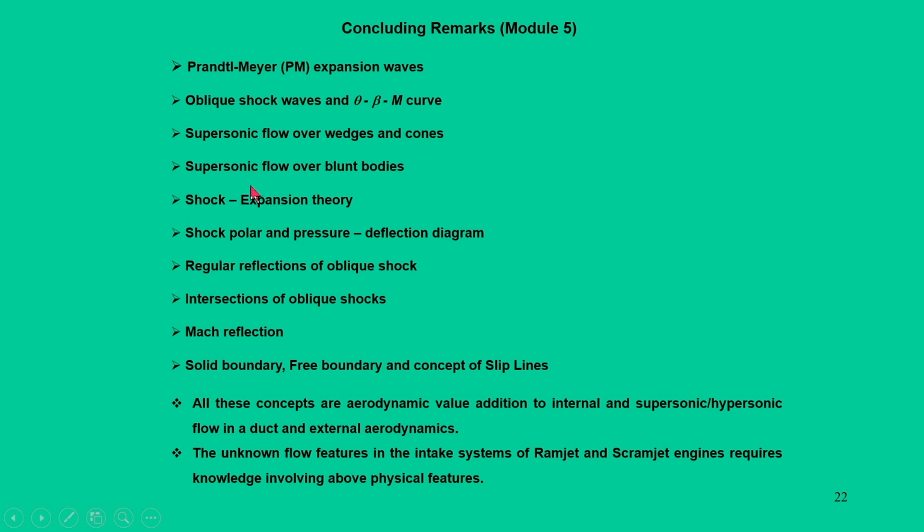We also gave some understanding of shock expansion theory, where there is a simultaneous presence of shocks and expansion waves, and this gives the concept of lift and drag theory in the design of airfoils. Another way of graphical representation that we made is shock polar and pressure deflection diagrams. These two diagrams are very vital to study some flow physics in the supersonic environment.